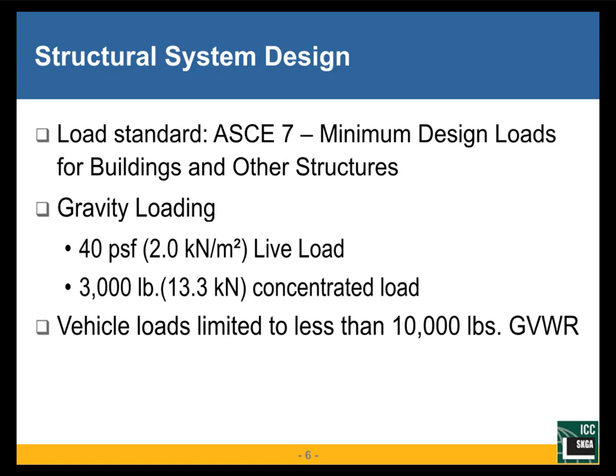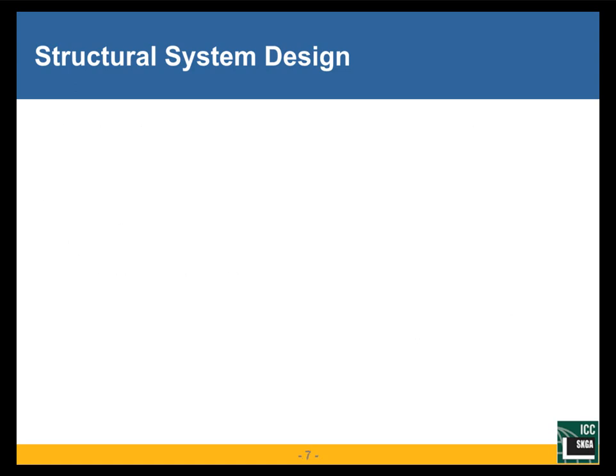There is research that is going to be sponsored by the Prestressed Concrete Institute to study the effects of axle loads, that is 2 wheels, and fatigue, based on increased load conditions in order to determine if there is a need to increase the criteria. But right now, this is the criteria that we work with.